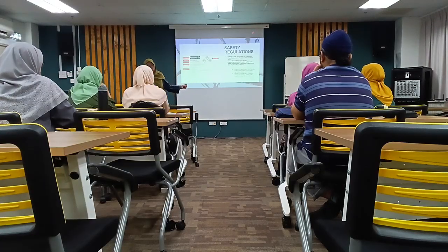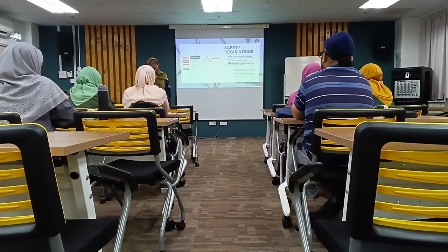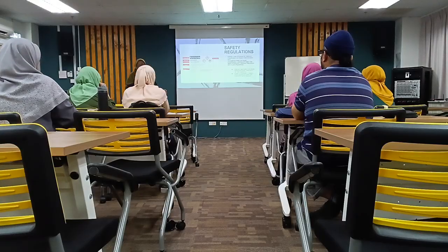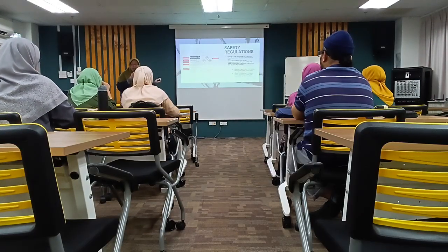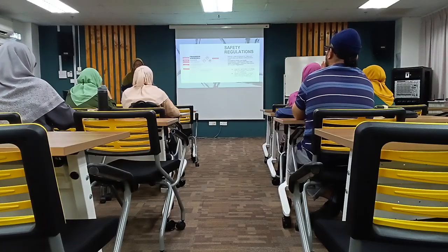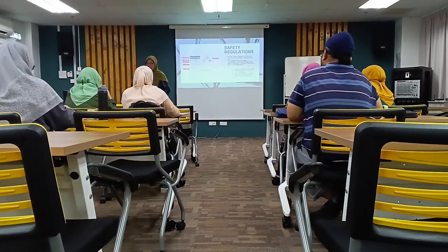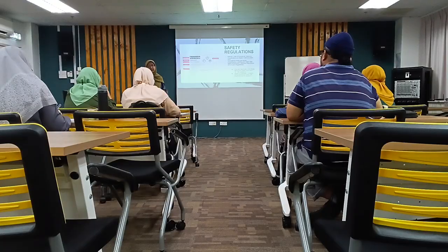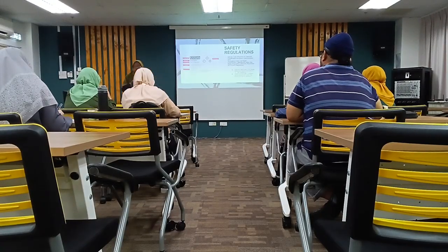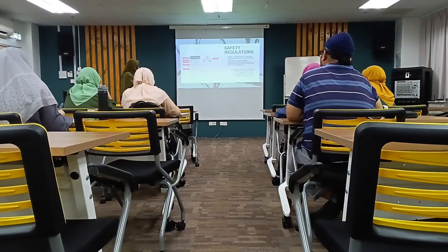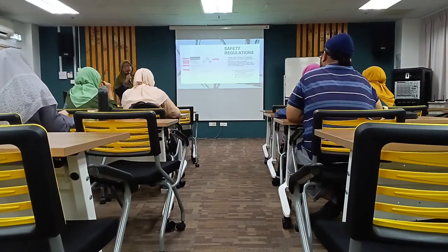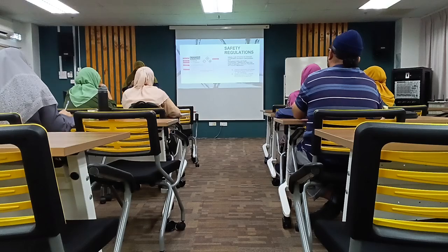Another piece of information that is also important and is always missed out is the safety data sheet of the chemical. On the bottle, it should have 6 pieces of information. For the safety data sheet, there should be 16 pieces of information present. You can refer to GHS for what those 16 pieces of information are that should be communicated through the SDS.